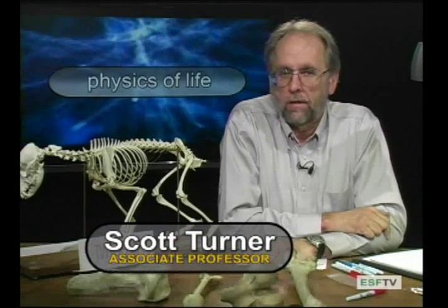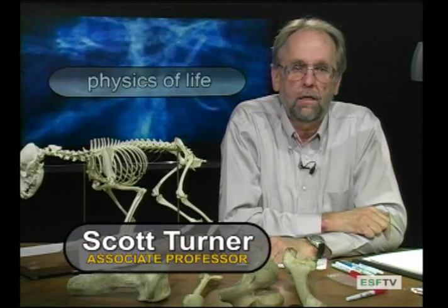Good day to you. In other modules, we've been speaking about the Young's modulus of elasticity and how it governs the relationship between stress and strain. And we emphasized in those modules that the Young's modulus is a property of materials rather than objects. Objects have shapes, they have dimensions, and all those are very important, but Young's modulus is a measure of a material property. And so irrespective of how big, say, a bone is or what shape it is, all of those bones will have the same Young's modulus.